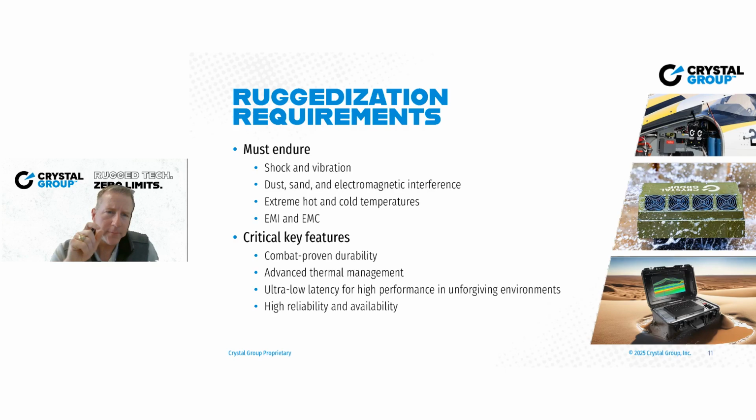And you're going to want to make sure that we're talking about this not at the vehicle level. This is what's happening. That's important and something that we want to make sure we understand. But more importantly, what is the environment around the box? Because you could get into a situation, particularly around shock and vibe, where you're over designing because your box is actually well isolated within, like, a ground vehicle, for example, or you're under designing because somebody said, oh, there's no vibration, but you happen to be sitting on top of, like, a howitzer.